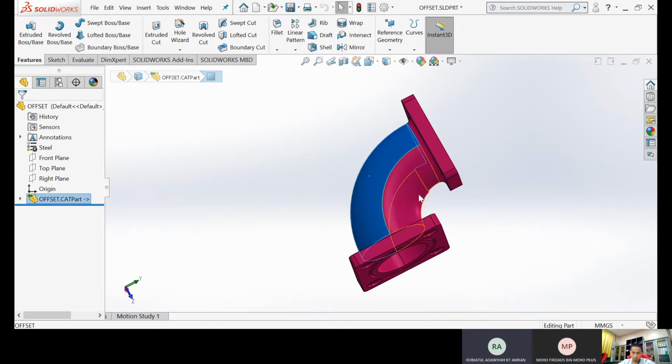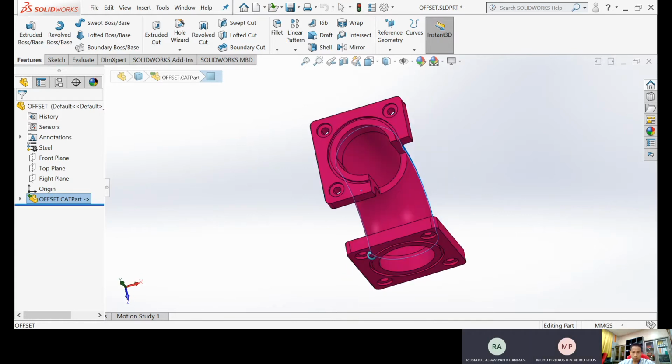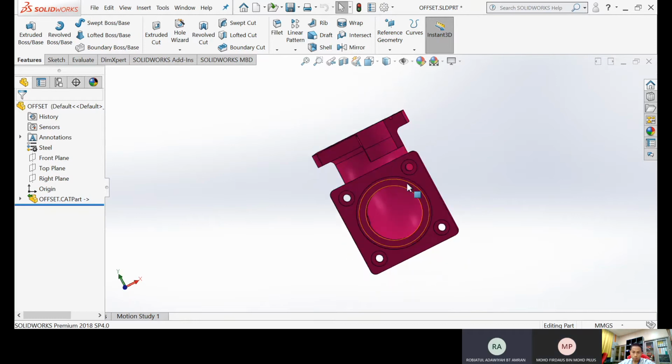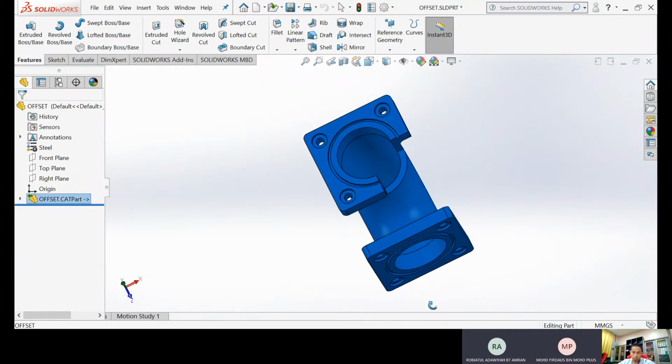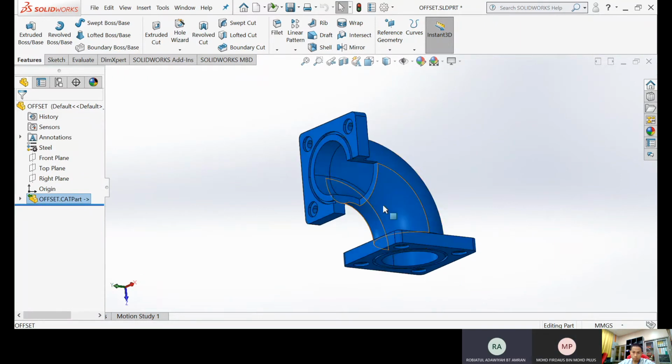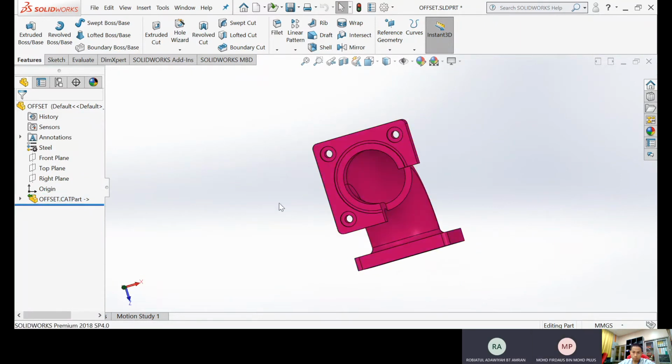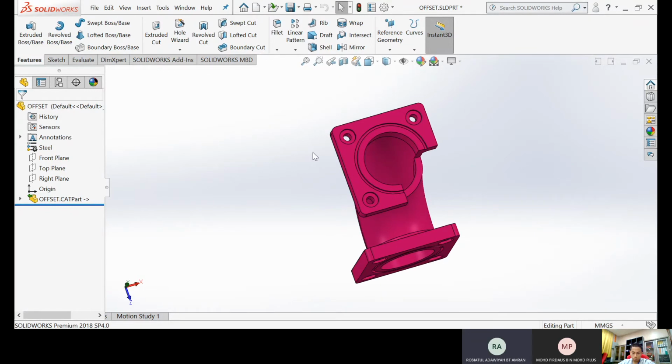Adjust curve fitting tolerance. Move the slider to the left to sample more vertices or points, making the curve fit more tightly to the STL edit or cloud. Move it to the right to loosen the curve fit. Add points that refine the curve position. Select the STL vertices to add curve defining points. Adds and displays breakpoints on the curve where two curves connect. You can see the connectivity at breakpoints to be contact, tangent, or smooth, and trim to the curve selected.